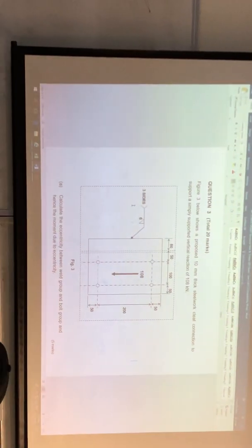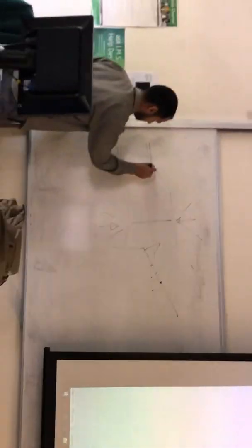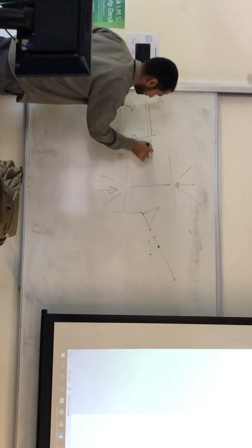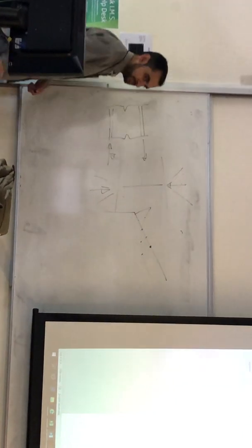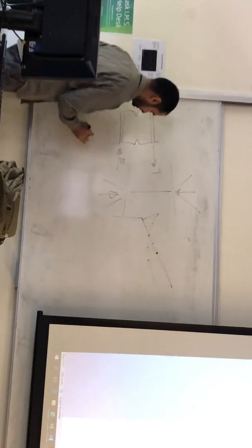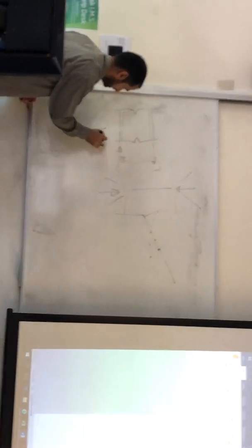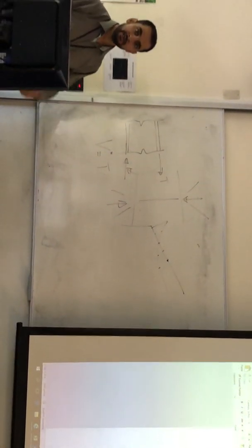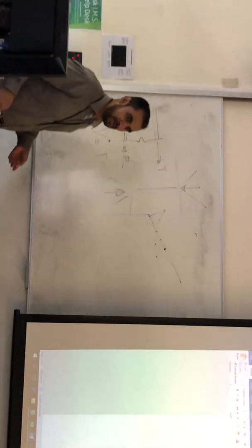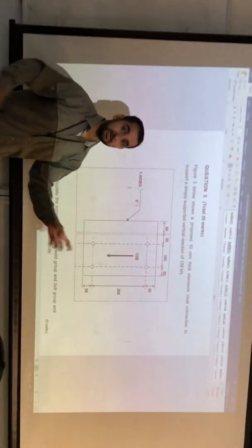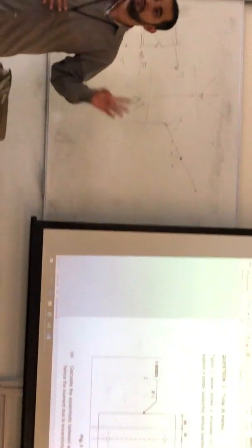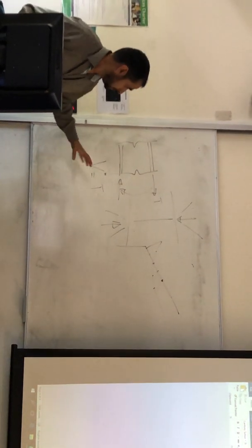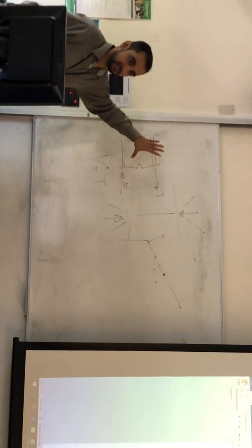There's the beam. So there is a moment, for example, that creates tension and compression. And the tension there, the force in the bolts is equal to that tension. That's it, right? You don't need to do all that, like some of you did, eccentric moment, where it comes from, all the X and Y and Z, but that was not the answer I was looking for. It's simple, the flange splice is the simplest one.